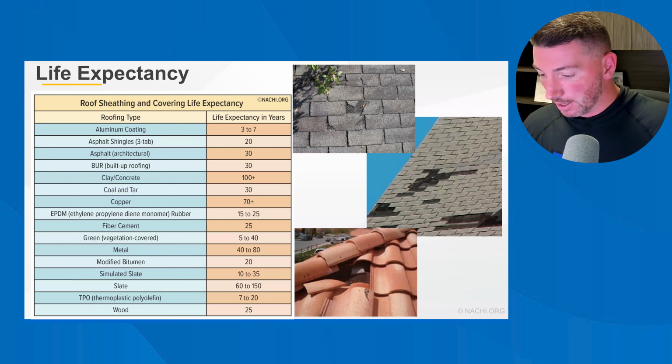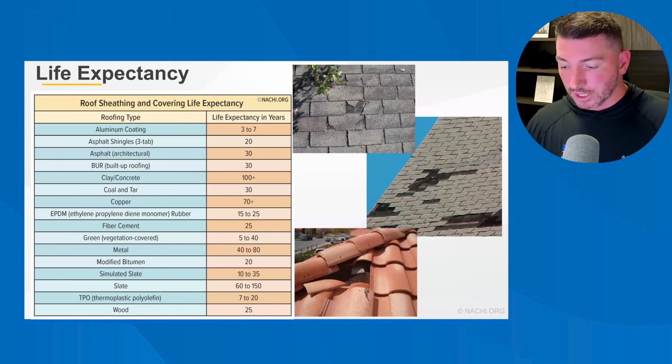But in any case, structural issues, both the roof sheathing and framing, can sometimes indicate structural issues revealed on the roof surface. Such problems can be apparent as cracked shingles or tiles above a structural defect. More commonly, there will be a wavy look in the roof caused by thin roof sheathing that is overspanned. So again, there's a minimum thickness allowed for roof sheathing.